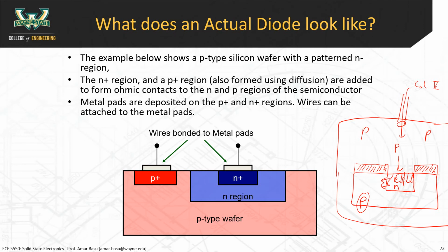And then, over very, very long periods of time, does this basically become useless though, due to diffusion? If you were to put it in the diffusion furnace for an infinitely long period of time? Basically, yeah. In principle, it could. If you kept it in there an infinitely long time, it would diffuse everywhere. But the distance it diffuses goes as the square root of time. So the initial amount of diffusion happens quickly, but to get it much further than that takes really, really much longer. It goes as the square root of time.